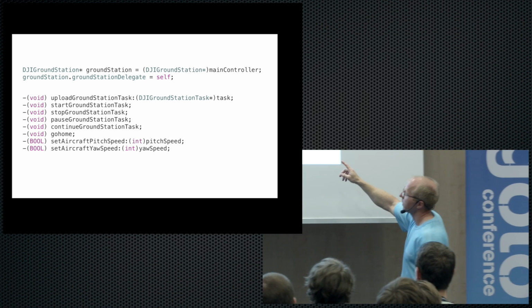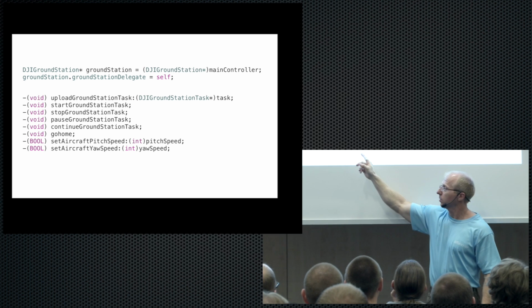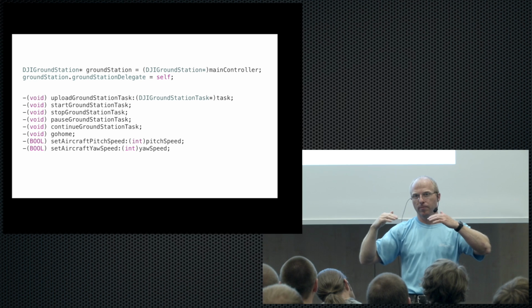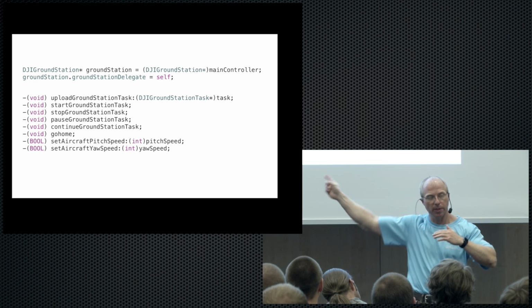Also, please note you can set the pitch speed or the yaw speed here. Setting the pitch speed doesn't mean that the drone actually starts to pitch. It's just that when at some point it does pitch, it will be at this speed.